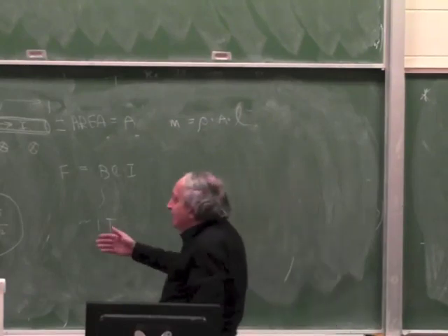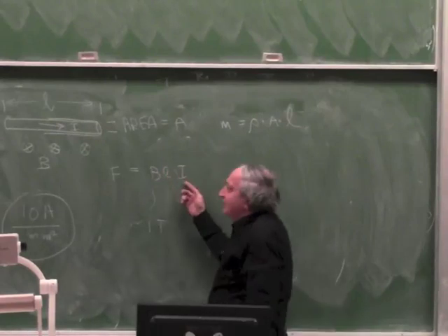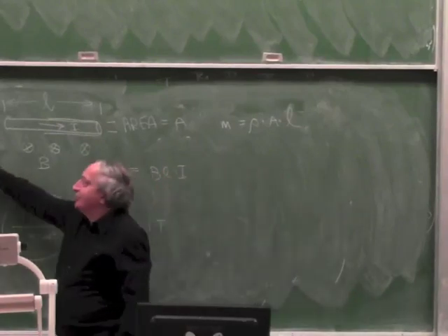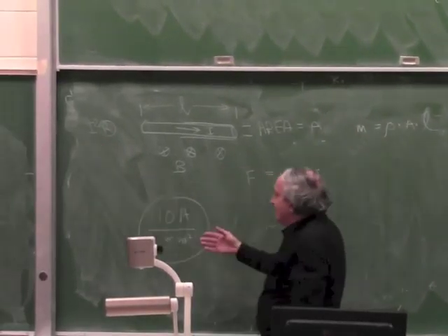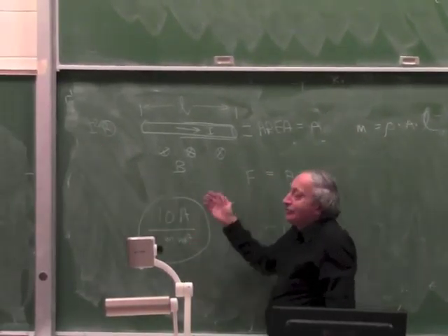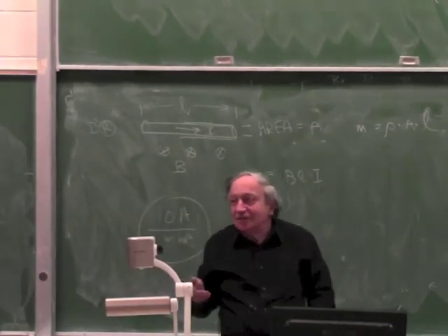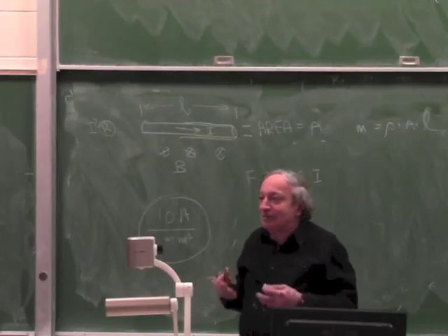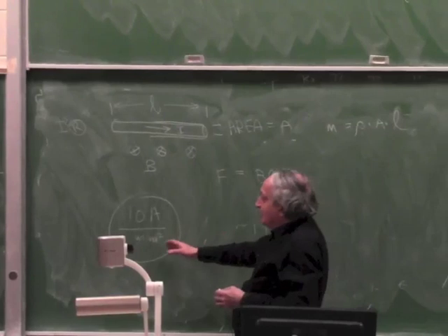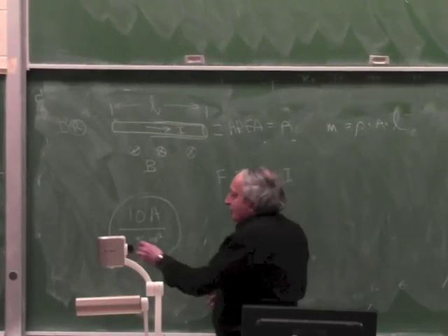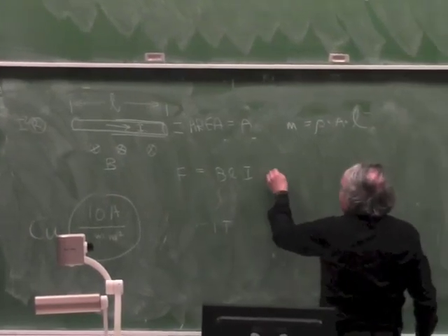Now if you run higher than that, the force will go up linear with I, but the heat will go up like the square. So you pretty soon stop gaining. Say if you double this number, you'll only double the force, but have 4 times the heating. So instead of 30 degree delta T, it'll go to 120 degrees above ambient, which is already pretty bad. So that's a good number to remember for copper. That's for copper. Okay, so this is roughly approximate.